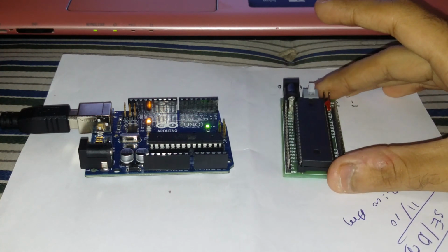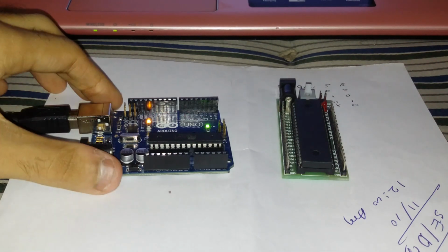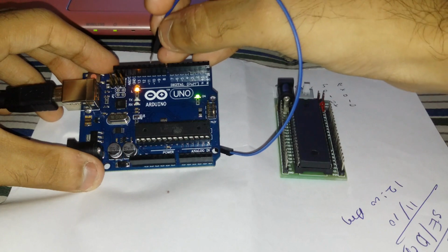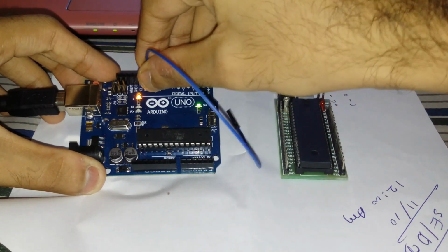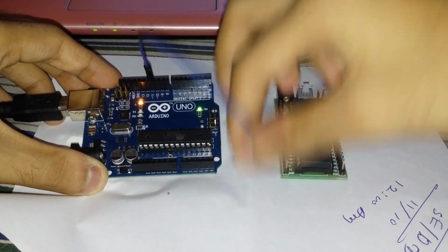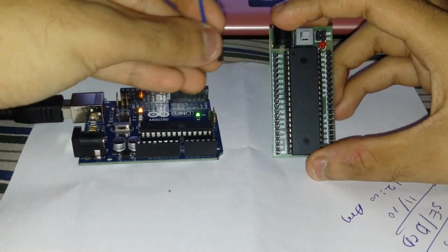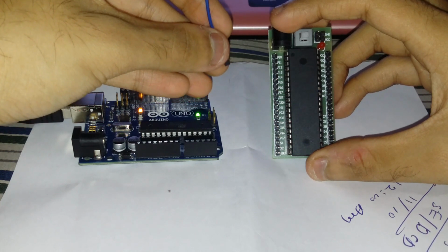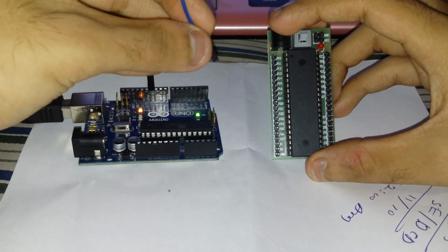Now we will start connecting here. Take the male female wires here. So the first connection that we have to make is pin number 11 of the Arduino. Alright, pin number 11. Okay, here 8, 9, 10, 11. Here we go. Pin number 11 of the Arduino gets connected. Yes, it's connected. Pin number 11 of the Arduino with pin number 6, that is the MOSI pin. I will come back to you on what this MOSI is and all that stuff.